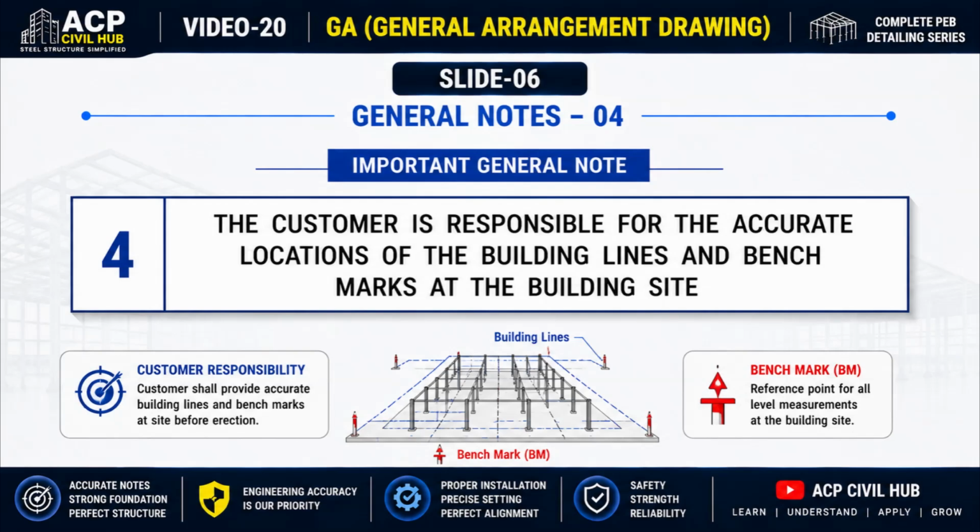Building lines are the reference lines used to position the entire steel building on the foundation. They ensure that every column, wall, and structural member is erected at the correct location according to the approved layout. A benchmark, or BM, is a fixed reference point that provides the correct elevation for the project. All foundation levels, column base levels, and structural elevations are measured from this reference point.